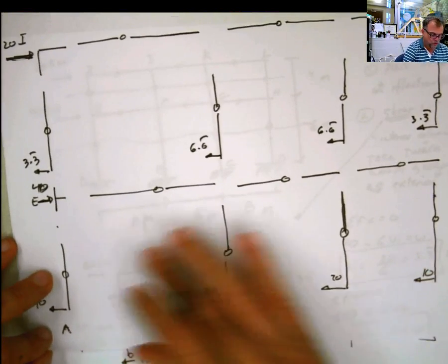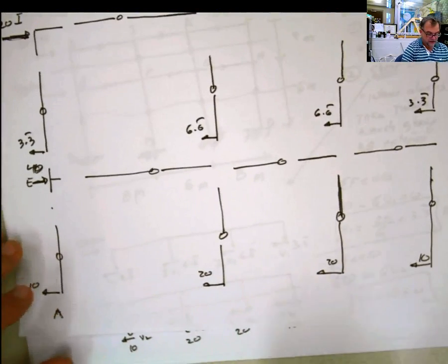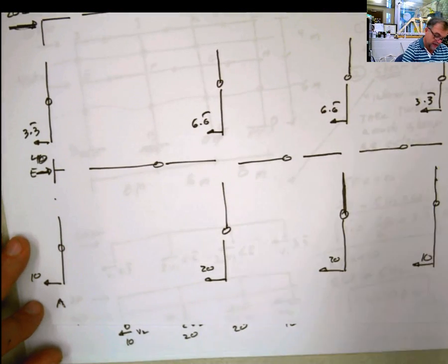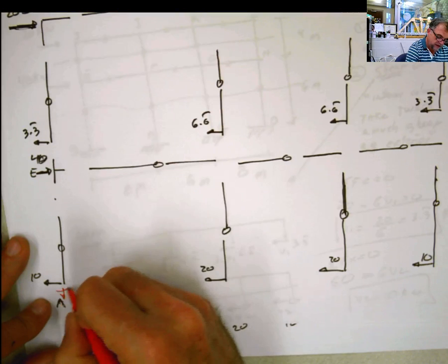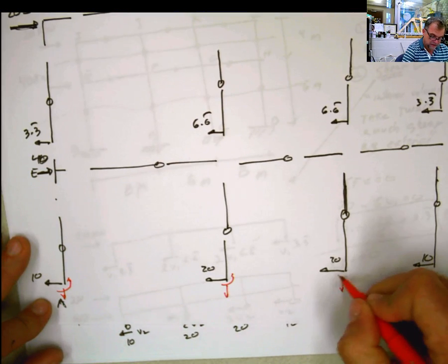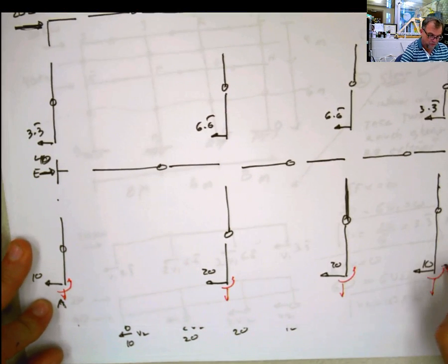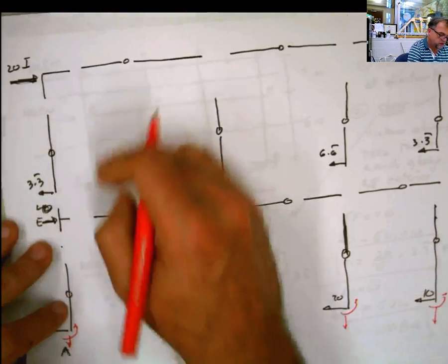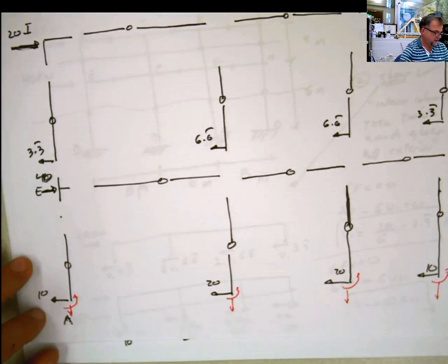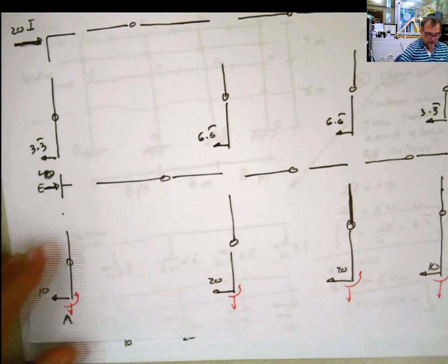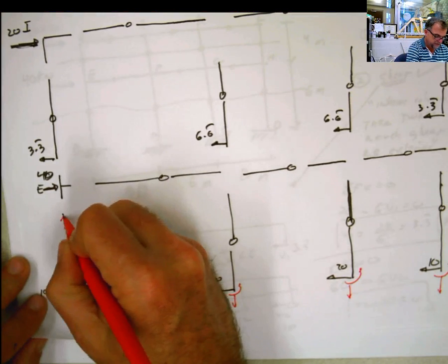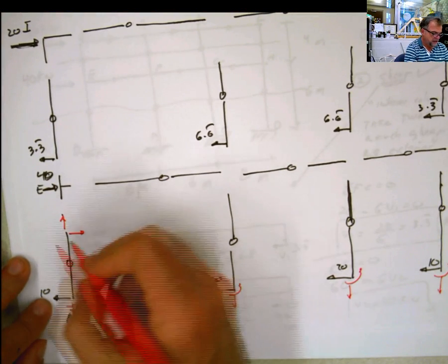Now, what do you do after having this mesh? Well, after having this mesh, remember this is a fixed support. If this is a fixed support, I have to have axial force here, axial force here. I have to have moment. I have to have axial. I have to have moment, axial, moment, axial, moment here also. Same situation with everything else. But now somehow we can start completing this. Why? Because I know that at this end also I'm going to have axial, this end axial, but I'm going to have also shear, and at this end I'm going to have also moment.